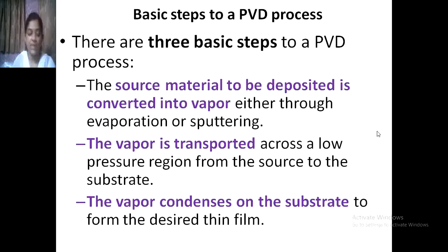Second, the vapor is transported across a low pressure region from the source to the substrate. Third, the vapor condenses on the substrate to form the desired thin film.